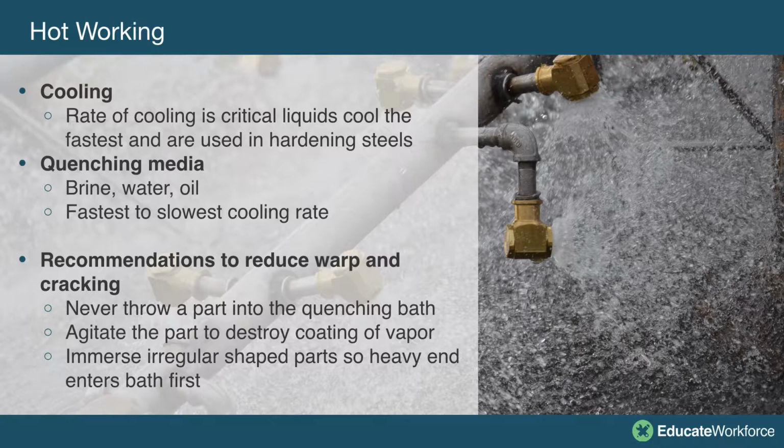When you're dealing with clad aluminum, they also have a solution heat treat, but one of the things that you'll also notice is a precipitation heat treat process, and that's nothing more than just an aging process, just letting it sit at room temperature, and it will continue to get harder as we go along. If you remember, we talked about D and DD rivets, which are icebox rivets. We freeze them and hold them at a specific temperature, and then we drive them in a cold state, and as they sit over time, they'll get harder. That's a precipitation type heat treat process.